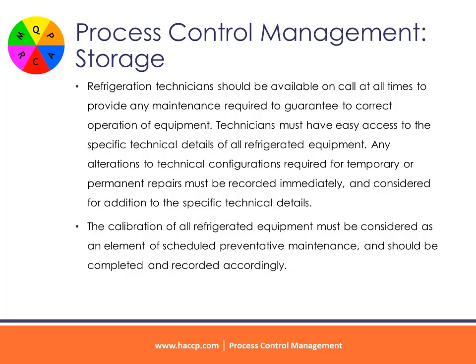Technicians must have easy access to the specific technical details of all refrigerated equipment. Any alterations to technical configurations required for temporary or permanent repairs must be recorded immediately, and considered for addition to the specific technical details. The calibration of all refrigerated equipment must be considered as an element of scheduled preventative maintenance, and should be completed and recorded accordingly.